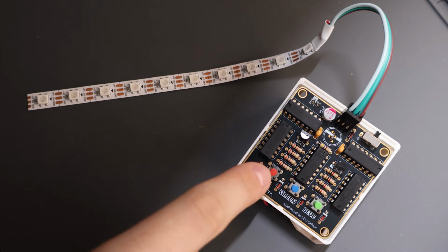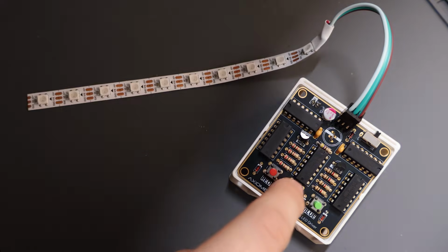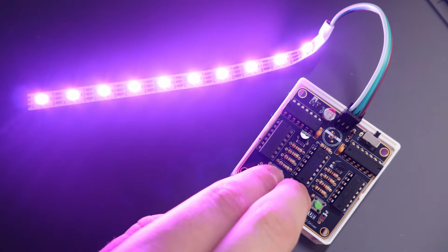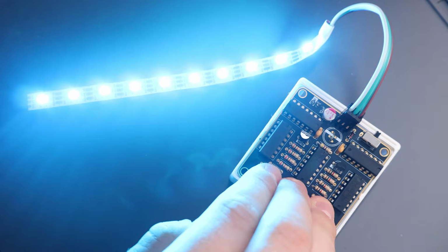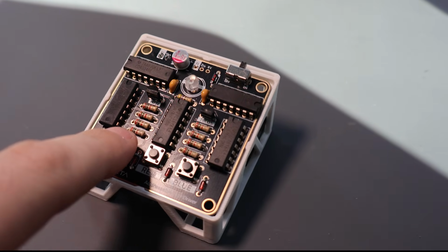After soldering all the parts and spending an entire day debugging, I finally got to the end. A self-sustained addressable LED driver without a microcontroller. 3 buttons, red, blue, and green. Hold 2 at a time and they mix for purple, cyan, or white. 24 bits generated by an oscillator, a counter, and some logic gates. It also has an onboard LED, so you don't need an LED strip.